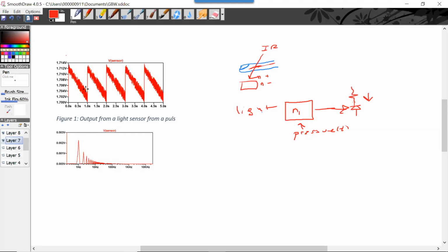And you'd want to know, if I needed to design a filter to get the part of the signal that I want, really the best thing to do is to take the FFT, right? And so, yeah, I have 1 hertz because when I took my pulse, I was relatively relaxed. So, 60 beats a minute or 1 beat per second.